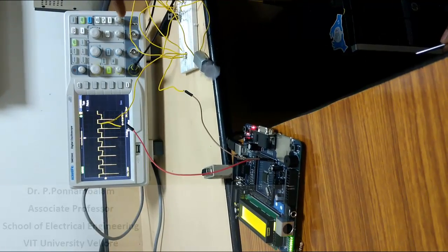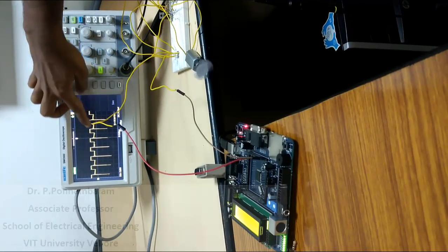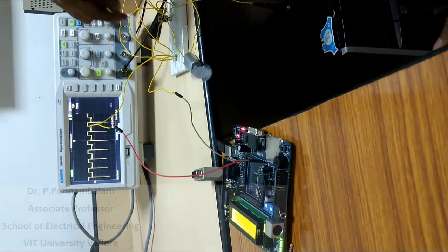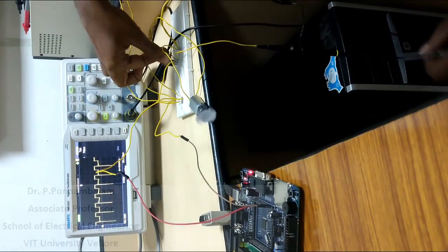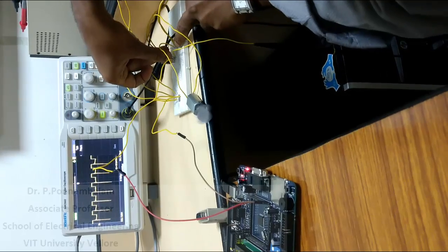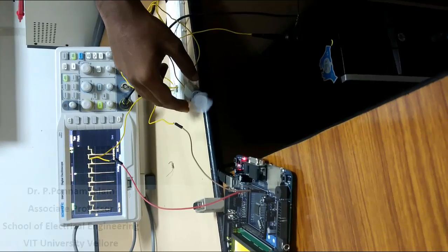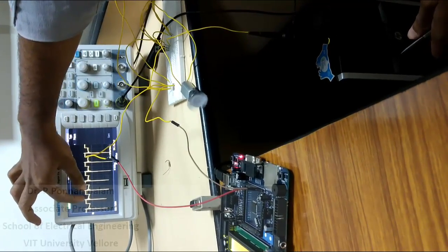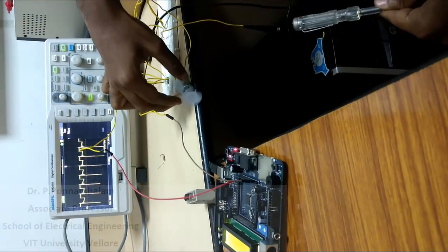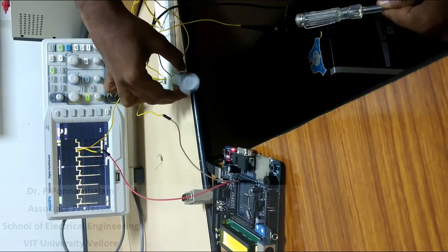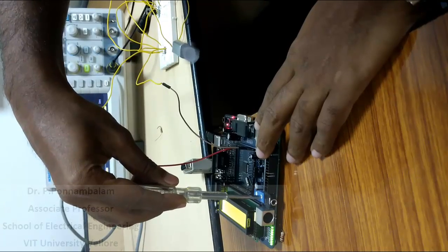Already we have done the circuitry with the load resistance. Now we are going to connect the motor with this one. You can see the waveform over here, and the motor is being connected in place of the load resistance. I have connected the load resistance also along with it. If you want, I can remove this one also. So now I have removed the load resistance, and you can see this is the on time and this is the off time. If I increase the on time, the speed of the motor will increase. So now I'll increase it by varying the ADC port.